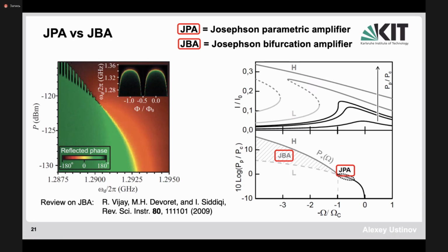So basically, parametric amplification is the most efficient at the point where the response of the nonlinear oscillator depends extremely strongly on the frequency of the drive. And that's where a tiny addition of the signal to the pump will make the output vary very strongly, and the spectral components will be the pump, the amplified signal, and the idler, as I described.